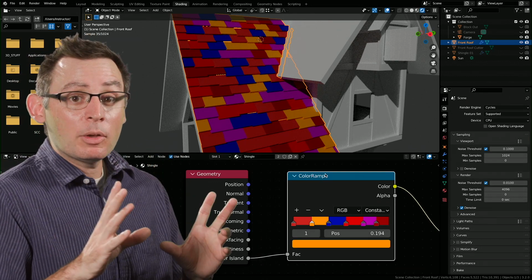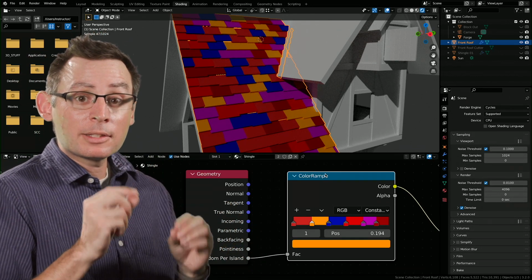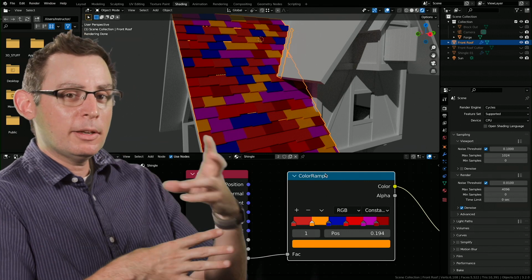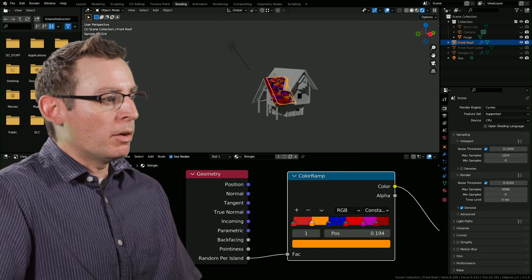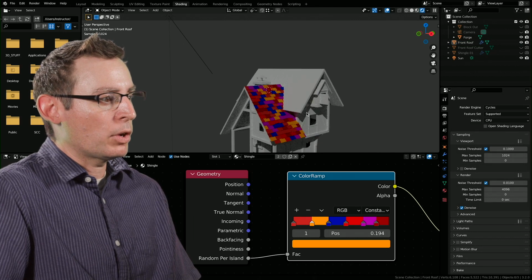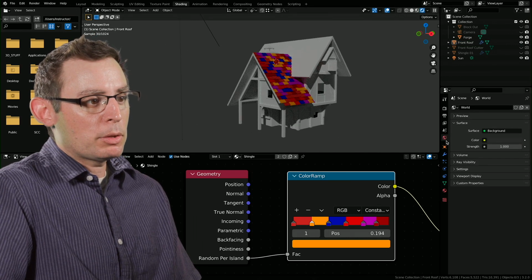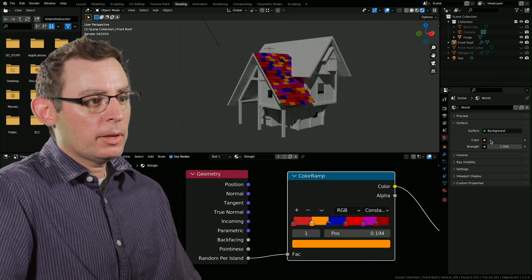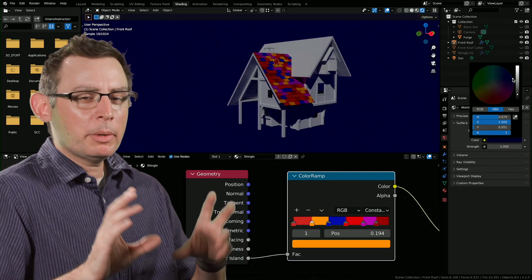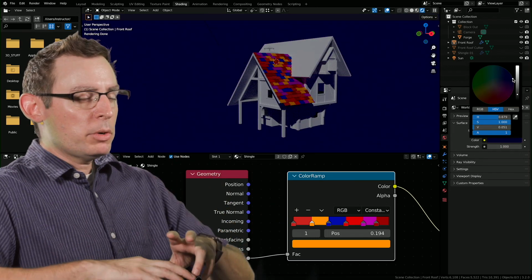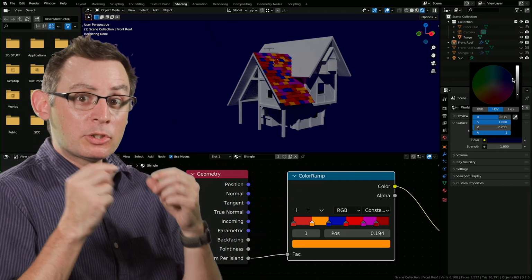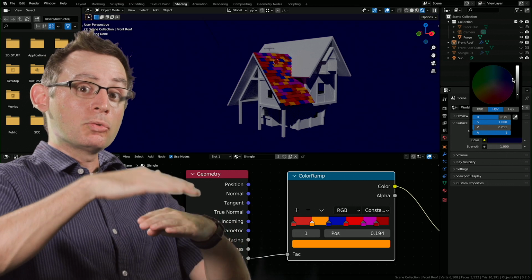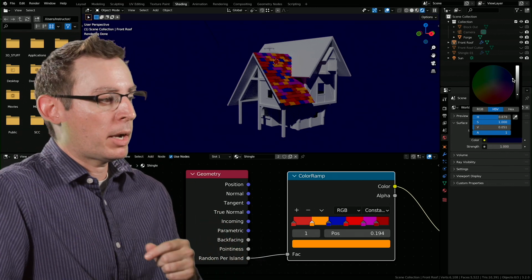Now, another thing that we only see inside of the Cycles rendering engine is a different sky texture. Right now, we're previewing the environment of our scene, and this is what it looks like. It's just kind of a gray space. If I was to look at the background, it's just a color. Okay. I can change that color, but I want to put a sky texture in there. I want to start flooding this environment with something that looks a little bit more photographic, not just a singular color, but a nice gradient of colors that happens in the background.